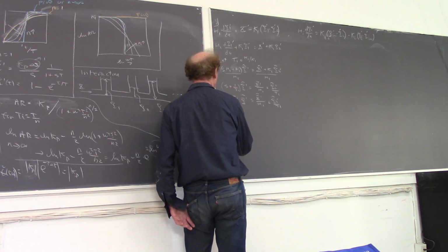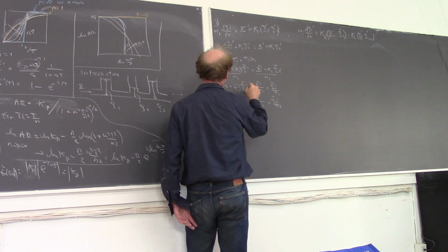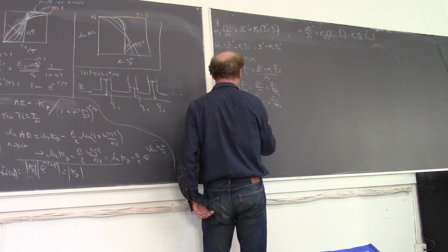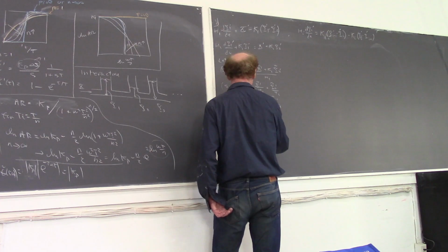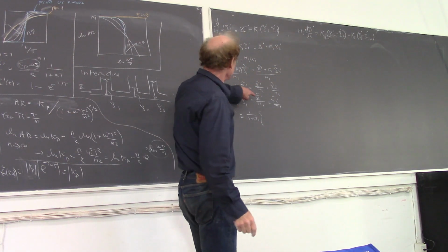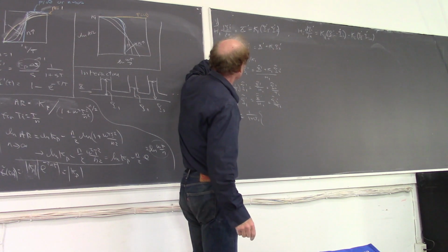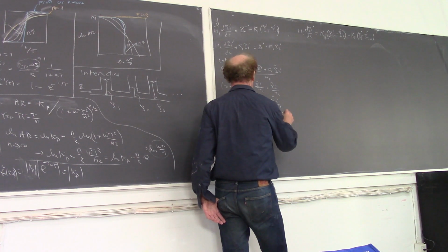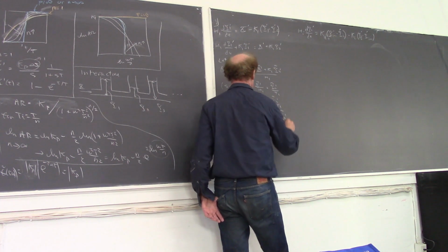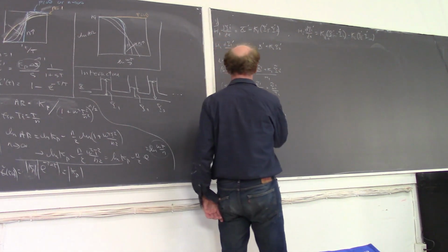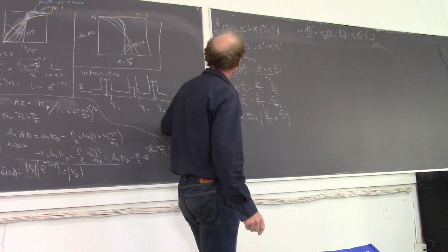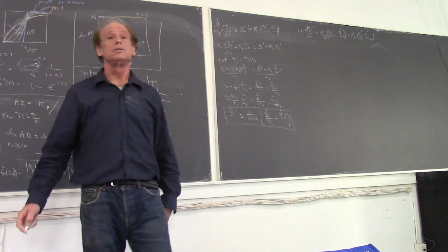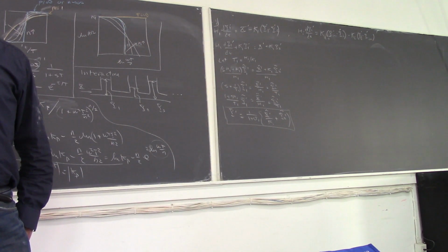So when I multiply through, I have y1 prime tilde is equal to 1 over (1 plus sT1) times T1 over H1. T1 over H1 is 1 over k1, plus y2 prime tilde. Again, I multiplied by T1. Did that algebra at lightning speed, but hopefully that's not too complicated.